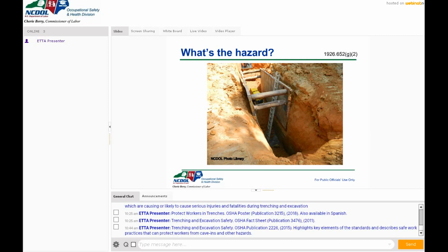All right, some trench boxes may have a brace down here too. Depending on what type of trench box, what type of load's going to be put on this right along here, you may need another brace in there to protect it from collapsing in on someone. So that's something you don't think about. When we ask to see the trench box tabulation tables, it will tell a person that. So everyone's got the good answers on what they're saying.